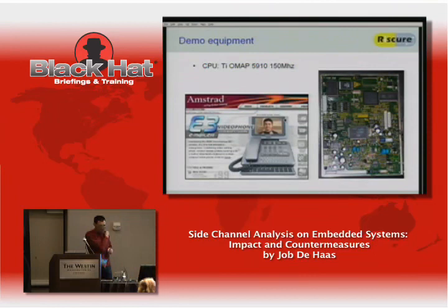So what I have here is something I just got off eBay because it's nice and cheap and still contains a full Linux embedded ARM CPU. It's an OMAP chip. It's one of the oldest TI OMAP chips that is now the big line of phone chips. So probably if you've got Nokia phones, and a lot of brands of phones run on the OMAP chip these days. But it's a very, very old generation. It doesn't even have hardware crypto. So everything I'm showing is a software implementation of crypto to make it more visible, because else we'd be looking at really just 2 or 3 samples, and now you can really visibly see the signal of a crypto operation.